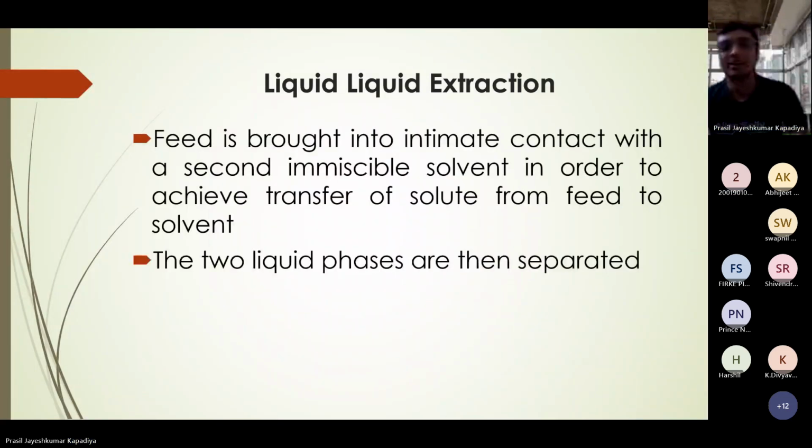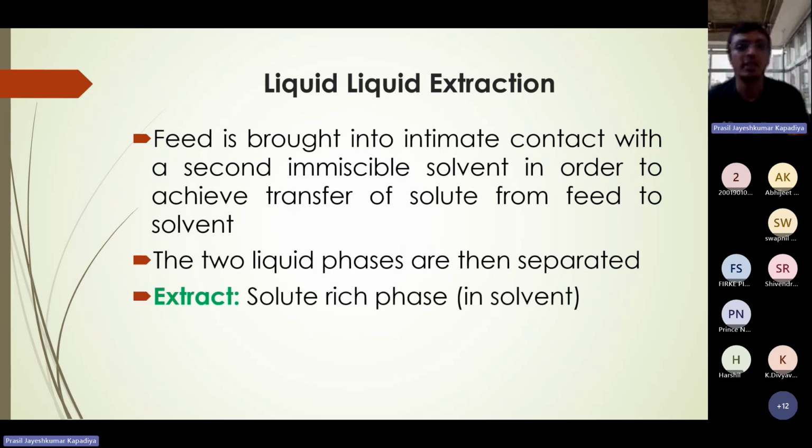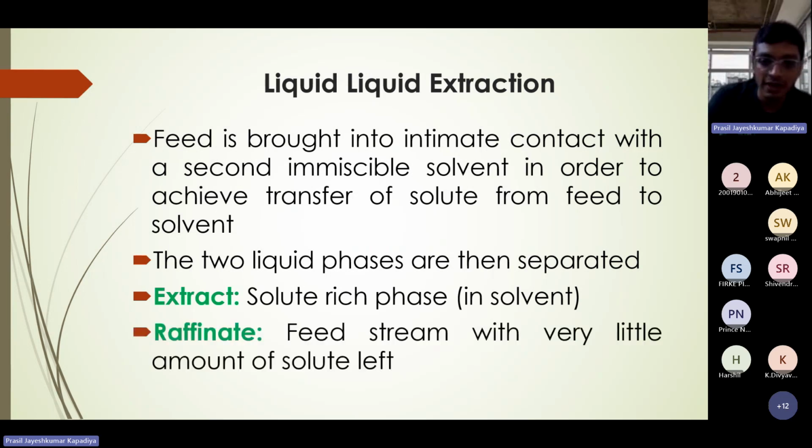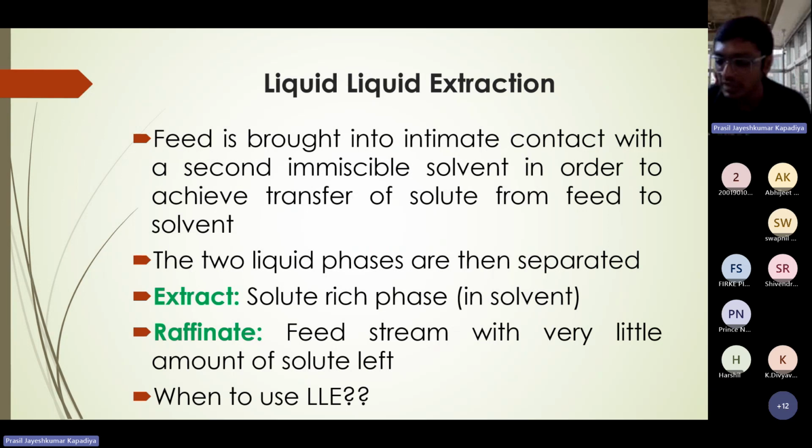Now the two liquid phases are then separated. Let's say solvent plus the A that we wanted to separate from feed. So A and C we have, then we can separate A and C, two liquid phases: extract and raffinate phase. Extract is the solute rich phase in solvent, and raffinate is feed stream with very little amount of solute left. So question, when to use LLE?